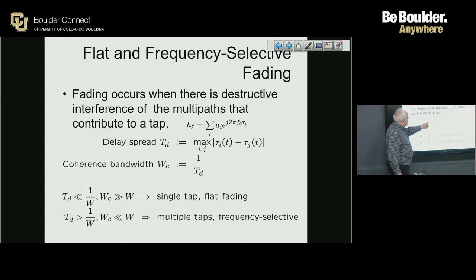The inverse of the delay spread is called the coherence bandwidth of the channel. And for a Wi-Fi system, this delay spread number, which is sort of the average amount of time it takes a reflection to reach a receiver, is on the order of 50 to 100 nanoseconds. So that's a key point because you have to use that in our system design.